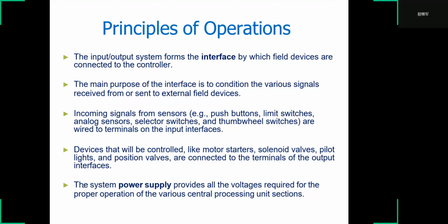The devices that will be controlled, like motor starters, solenoid valves, pilot lights, and position valves, are wired to the terminals of the output interface.